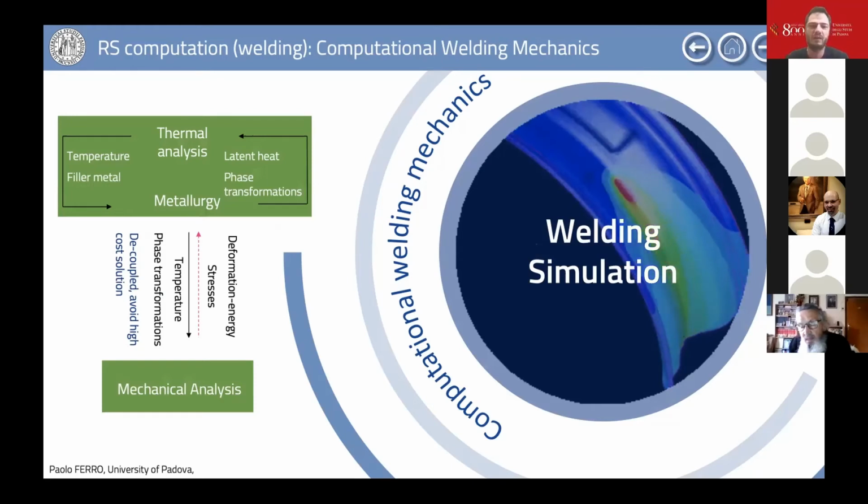In particular, when we try to model a welding operation, we need to use computational welding mechanics techniques. Let me consider this simplification. First of all, we have to simulate the thermal metallurgical loads induced by the welding during the first part.